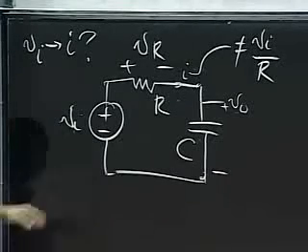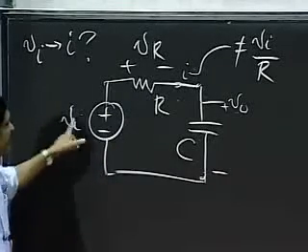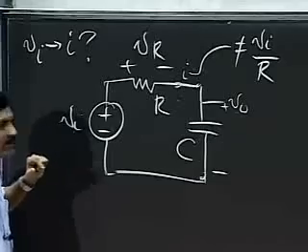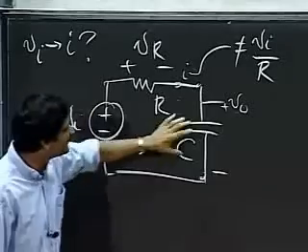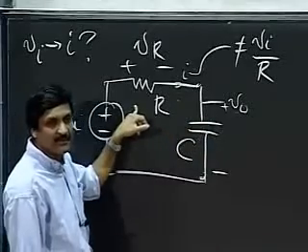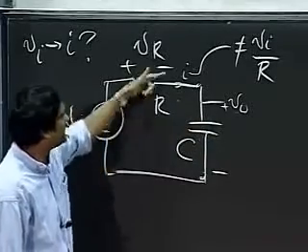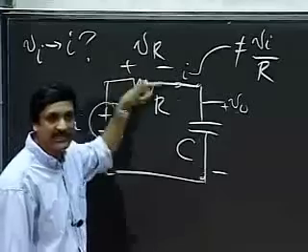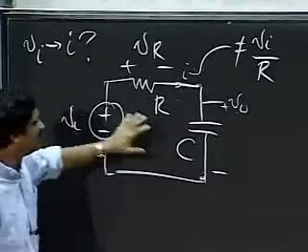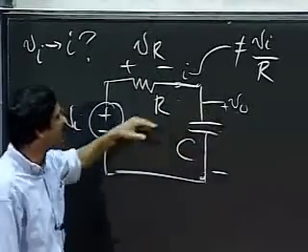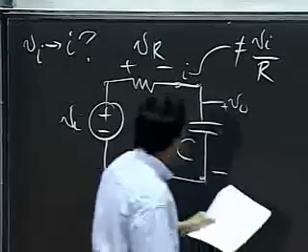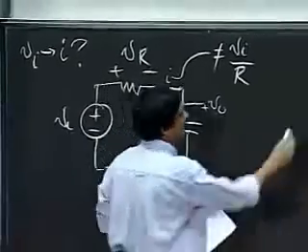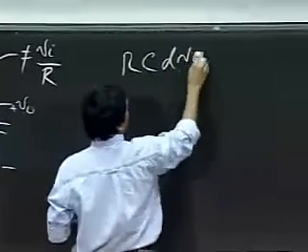But unfortunately, I is not equal to VI divided by R. You know that. Okay, I relates to VI minus the capacitor voltage divided by R. So I is not simply VI divided by R for all time, but I is really VI minus the capacitor voltage divided by R. And in fact, when we did RC circuits, you wrote this equation to represent the dynamics of the circuit.